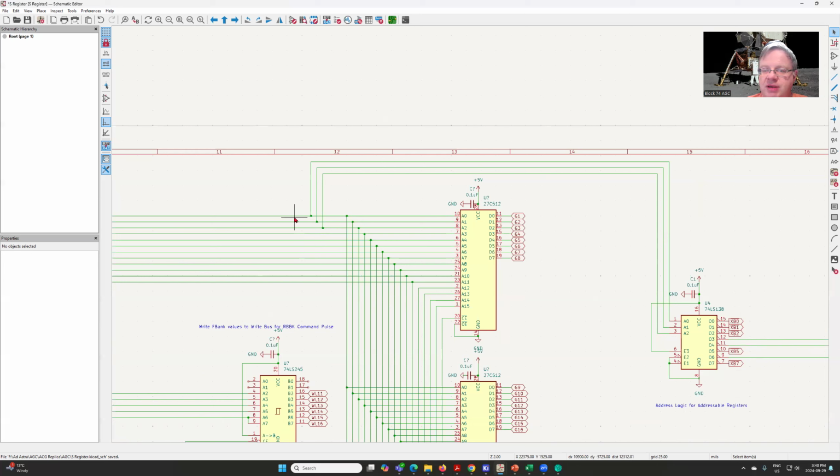So we basically pull off our low 3 bits off the S register, and then we just run it through this basically 3 to 8 decoder, and that'll allow us to generate our XB0, XB1, XB2. This is actually our XB3 and 4, our XB5, XB6, and XB7. So these will actually go out onto our main bus because we use them as inputs for accessing the A register, the L register, and the Z register. So these are where we generate those particular signals from.